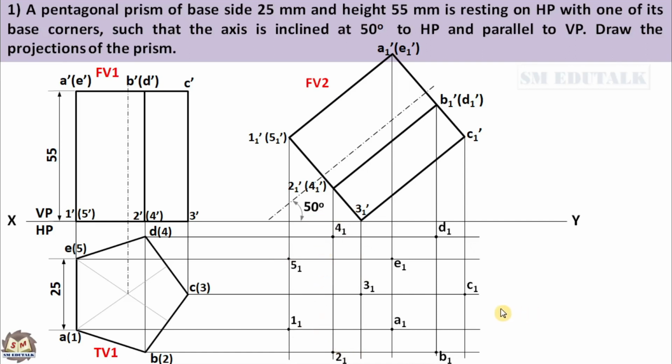We don't know the final shape of the top view. Whatever the shape, its boundary must be visible. It should be drawn by a continuous thick line. Hence, join all the outer points by a continuous thick line to create a boundary of the top view. This is only the boundary of the top view. We have to find the other visible and invisible edges in the object.